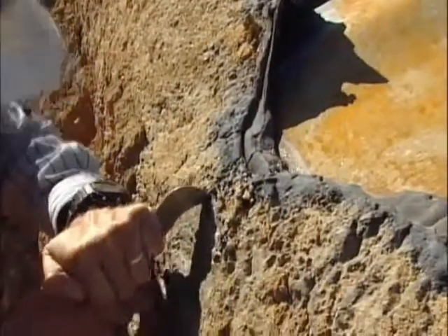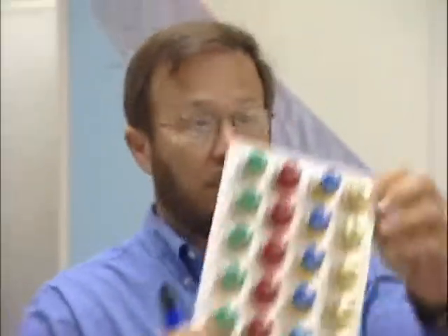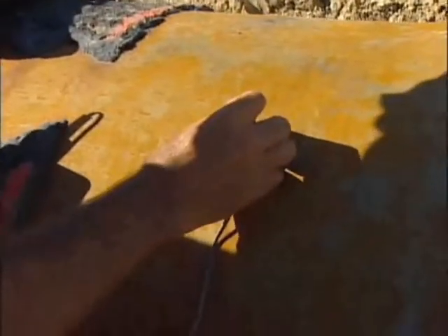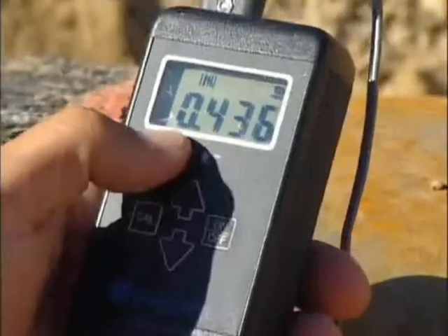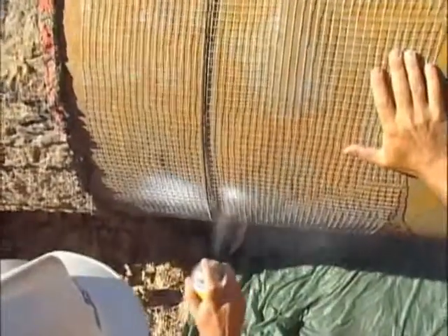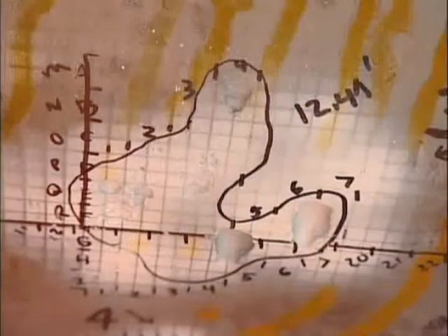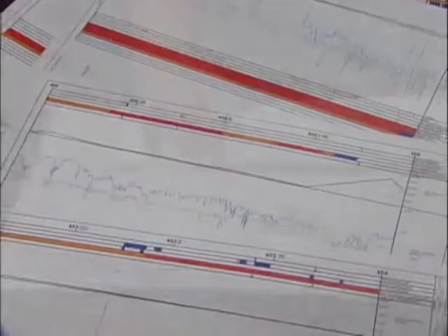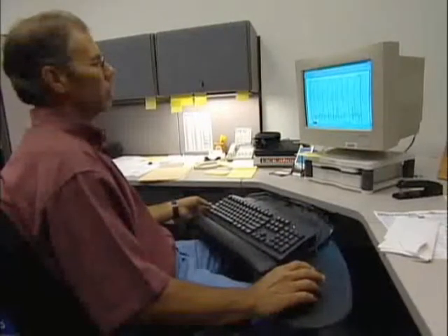analyzing any corrosion products found, including testing for microbiological influence, testing the pipe using magnetic particle testing, ultrasonic testing, and possibly even radiographic testing. If corrosion is found, detailed maps of the corroded area are made to assist in remaining strength calculations. Once all the as-found data are collected and evaluated, the results are combined with other pre-assessment and indirect inspection data to help the engineer understand the root cause of any conditions or integrity concerns that are present.